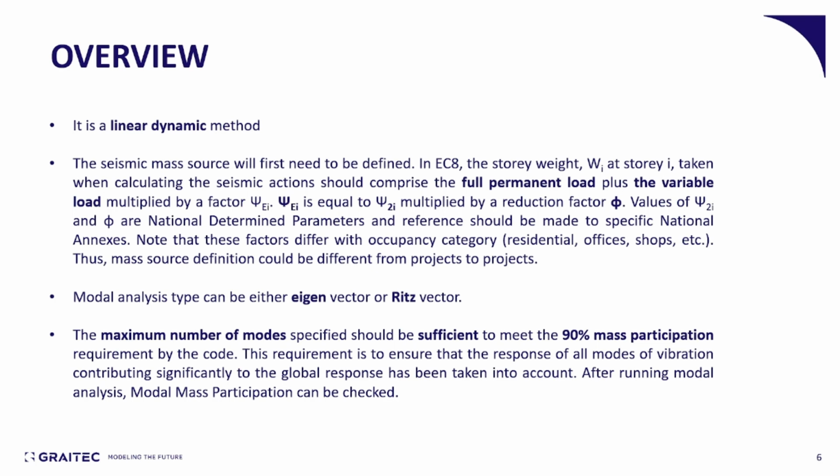We are going to discuss the difference between those two in the next slide. And of course, there is the following rule in order to be sure that modal analysis has been performed correctly. The number of modes that the solver will provide us needs to be sufficient to meet the 90 or 95% mass participation.